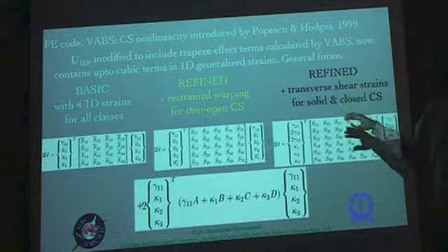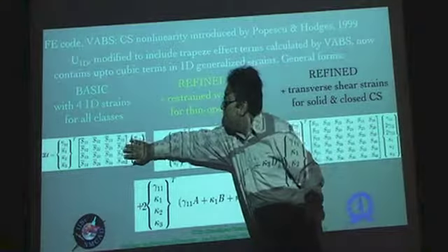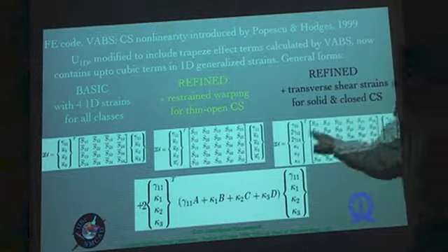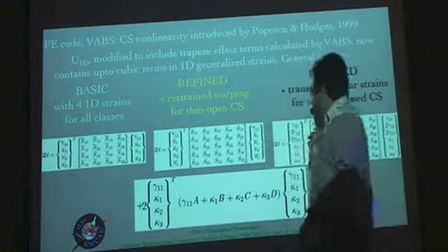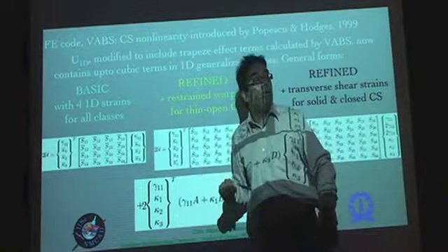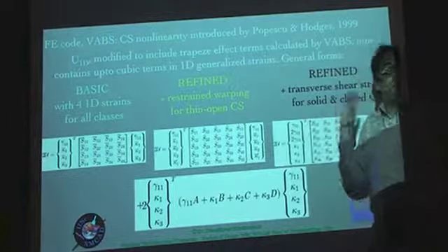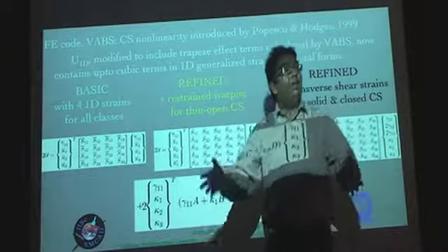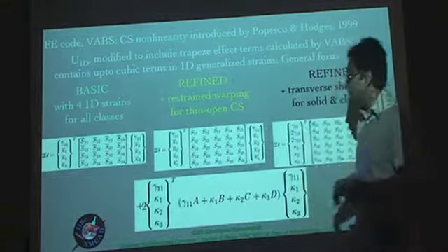Next, over and above this, all these are linear models, be it this 4x4 model, this 5x5 model, or this 6x6 model. Here we are talking about all of these S's or S hats or S bar quantities all being constants determined purely from the material distribution, the material properties, and the geometry of the cross section.